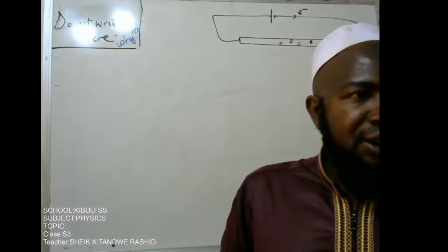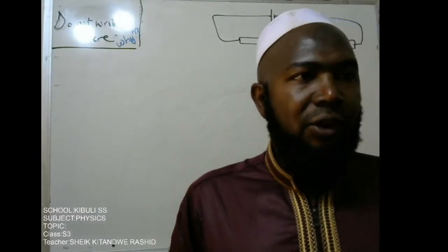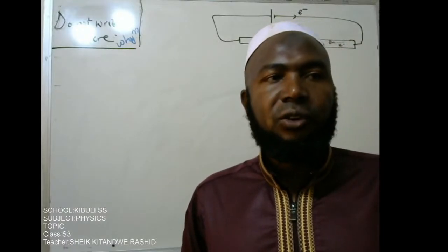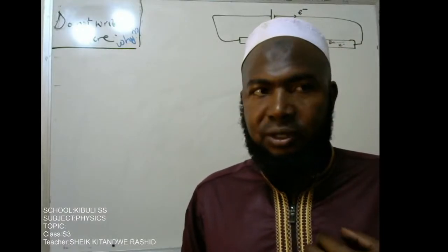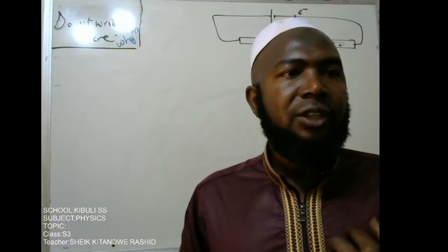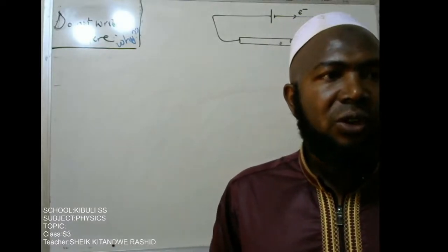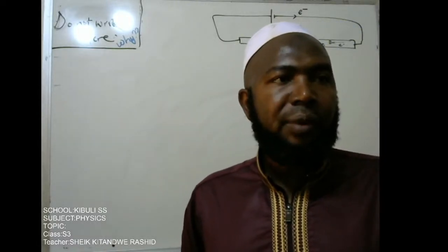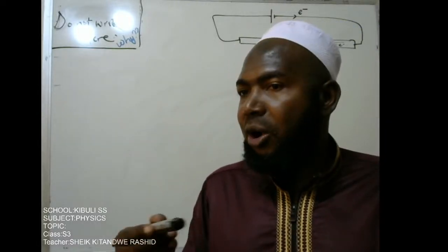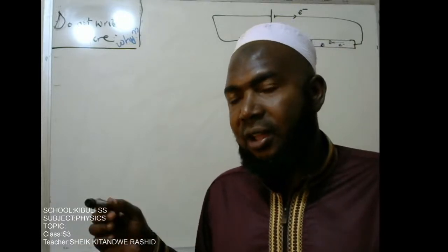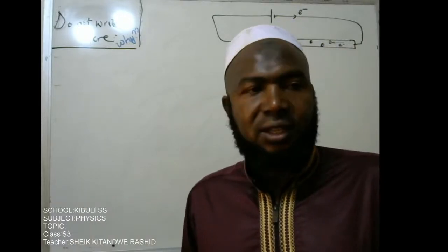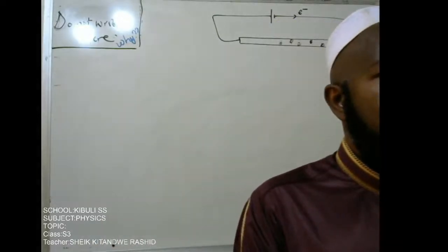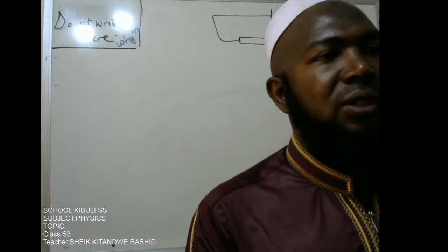Now the heating element is made of nichrome, a combination of nickel and chromium metals. The wire is used because it does not oxidize when it becomes red hot. The purpose of making it coiled is to increase the surface area and distribute the heat easily. So that is as far as heating elements and heating are concerned.